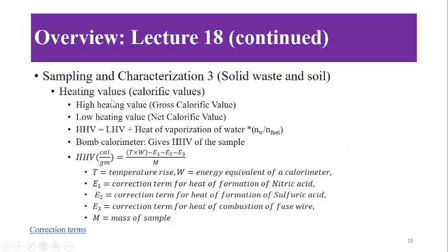Next, the heating values of solids were discussed, of the fuel, the high heating value as well as the low heating value. The difference between the high heating value and the low heating value is the heat of vaporization of water. So the high heating value includes the heat of vaporization of water.